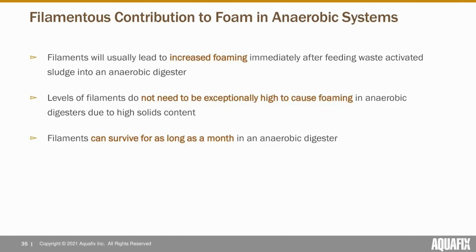All right, so filaments usually lead to increased feeding or foaming immediately after feeding waste-activated sludge. Like I mentioned earlier, there's that example with the thermophilic digester. We were never able to get an actual sample of filaments in the digester. We knew they had a lot of filaments in their aerobic process, but they were breaking down very quickly, in like 3 to 4 days. So they'd foam for like 2 days and then it would stop, and they'd be sending the sample right as it was stopping, and there'd be a couple unidentifiable filaments present. And we were just kind of like, well, what's going on here? I guess this filament doesn't live very long anaerobically.